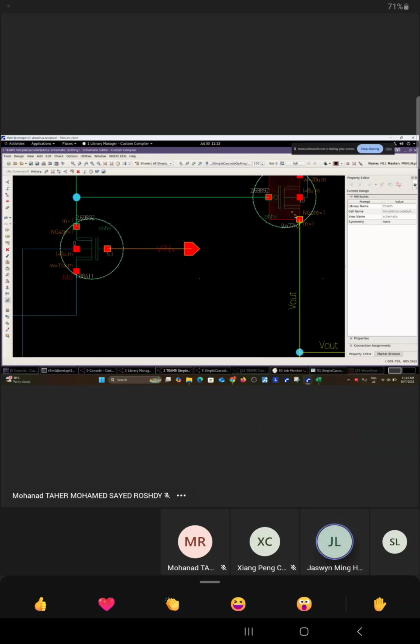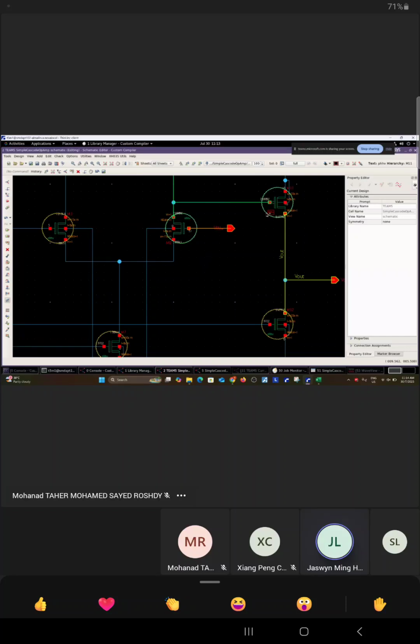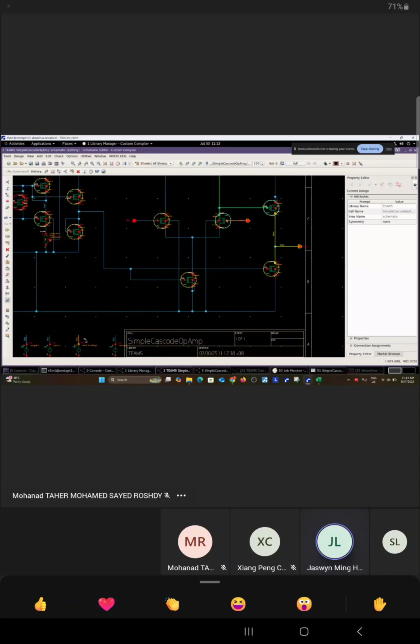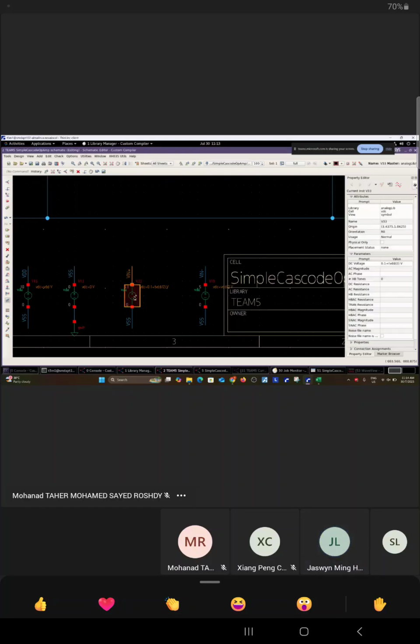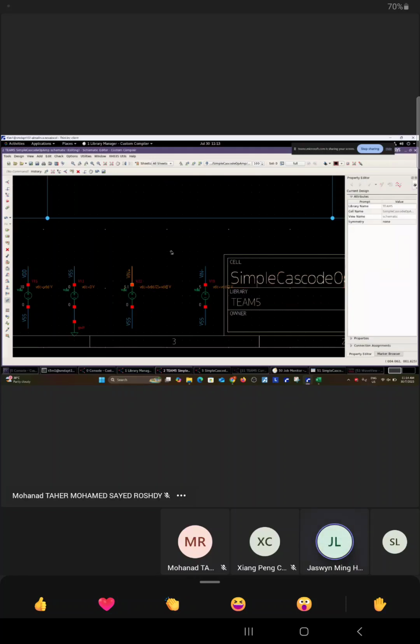Let's run the DC sweep that we have just now. Right now you put a VDIF at 0.1 here: VDD over 2 plus VDIF. Yes, correct.